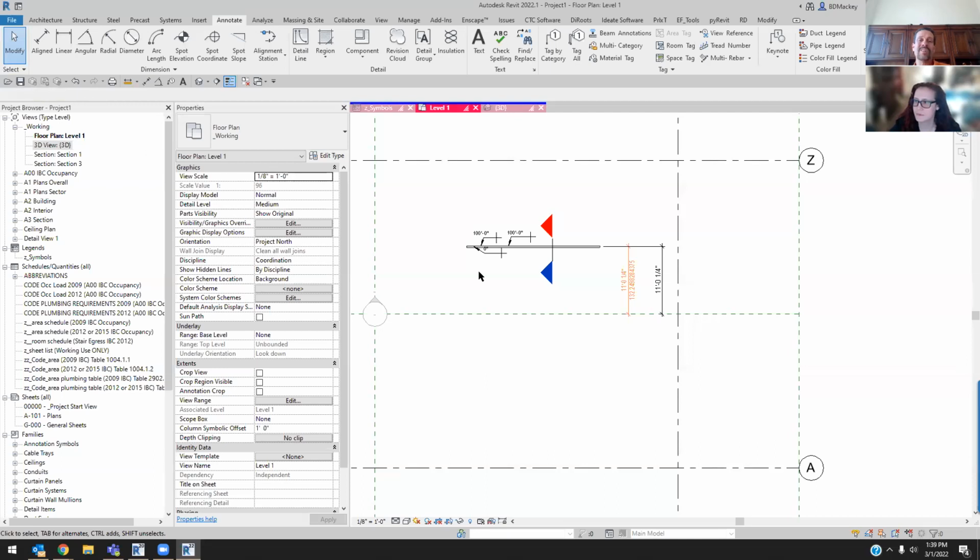Synchronizing also does not reload links. All it does is take changes from your central file, your BIM 360 model, and bring them down. If you open it, it will open up all the links live, and this is why I say it's almost live. If you open it, you're getting the latest version of that file that the discipline had pseudo live linked in. You would have to go in and do a reload on the link.